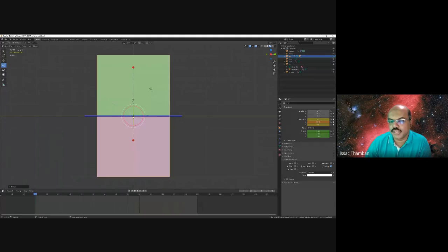And what about this distance? This distance is the distance of point P from the vertical plane. Or we can say that this is the distance of point P above HP, and this is the distance of point P from the vertical plane in the forward direction.